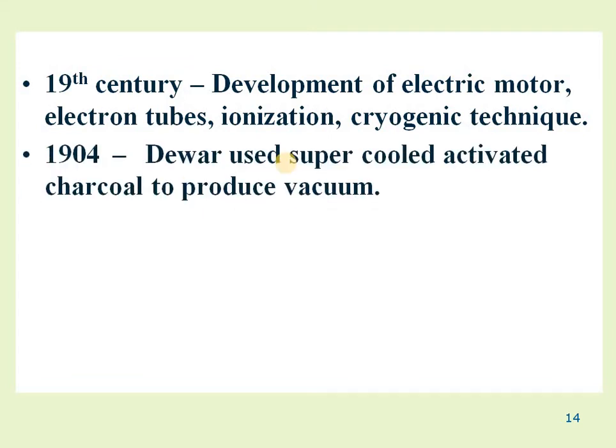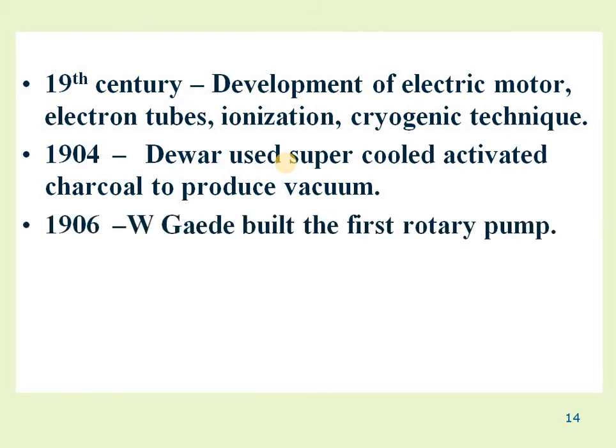And in 1904, Dewar used specially activated charcoal, a carbon composition. If you cool it down, its capacity to absorb gases becomes very high. Okay, the absorption rate is very high. So that way you can pump out gases.